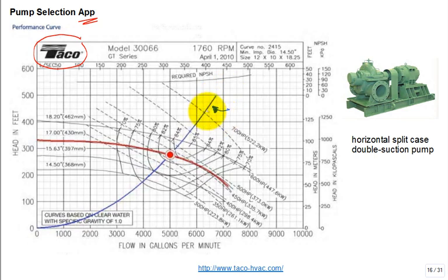On our pump curve, we recommend this model pump for your problem with this size impeller, and they color-coded it red and put it on there. And then they highlight the operating point. Boom, there you go. So at that operating point, it looks like, again, you could read off net positive suction head required, as well as probably push it a little bit to the upper right, the size of motor that you'd want.